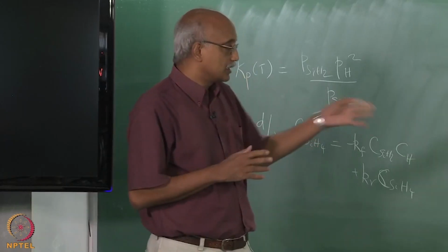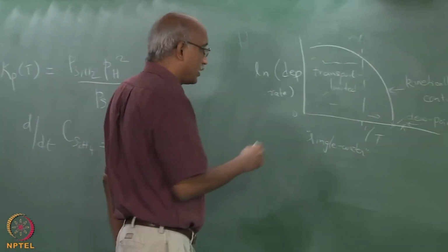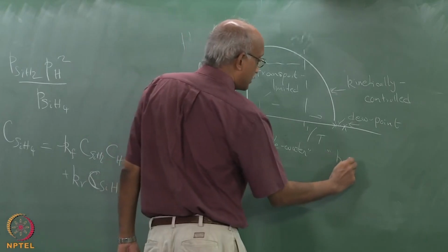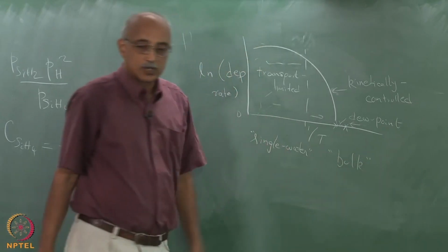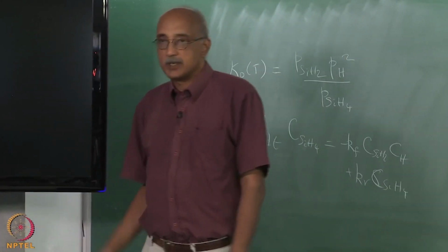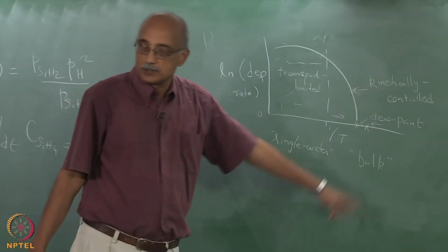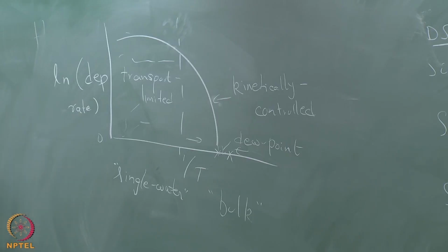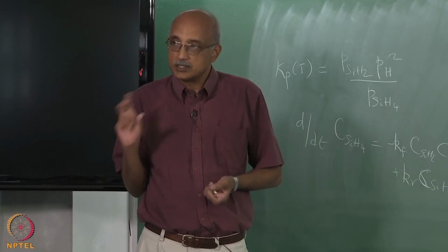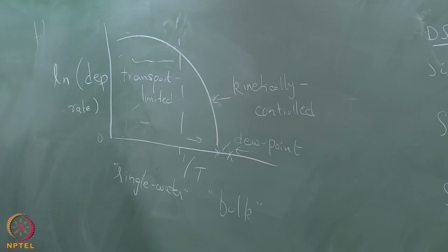So, there are a lot of very interesting things that you can actually extract from this work. From this figure, one of the things again is this is essentially suitable for bulk CVD, where you try to process many, many wafers at one time. So, if you are into volume production where you have to make a lot of product, then you are probably better off trying to operate in this regime. Whereas, if throughput is not your primary requirement, but rather the control and the purity and the uniformity of the film, then you are better off working in this regime.